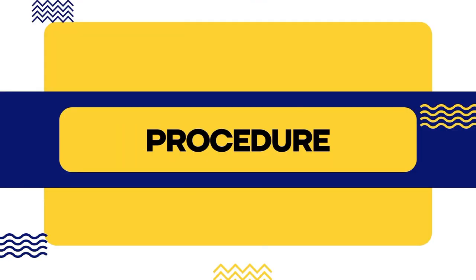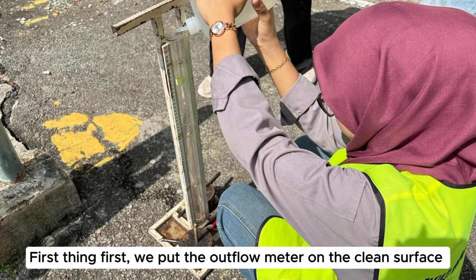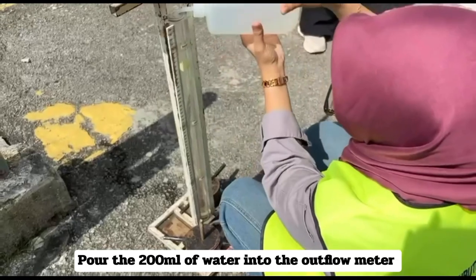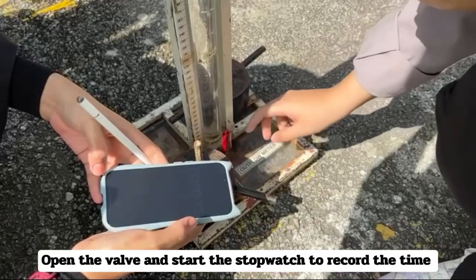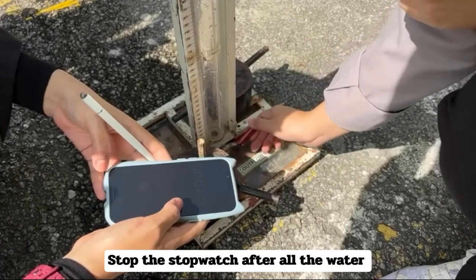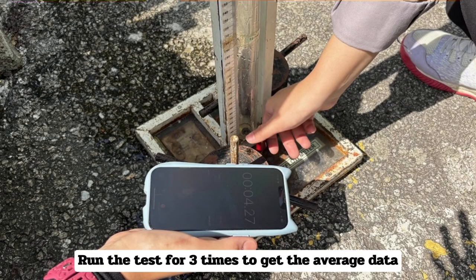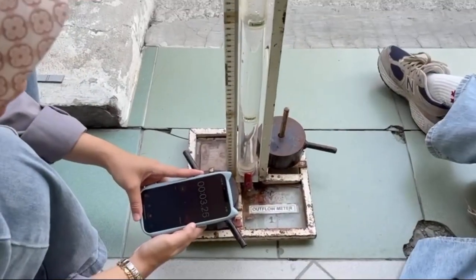The procedure for the surface drainage test is: first thing first, we put the outflow meter on the clean surface. Make sure the valve of the outflow meter is closed and pour 200 ml of water into the outflow meter. Open the valve and start the stopwatch to record the time. Stop the stopwatch after all of the water in the outflow meter comes out. Run the test 3 times to get the average data. Repeat the same procedure for the smooth surface.